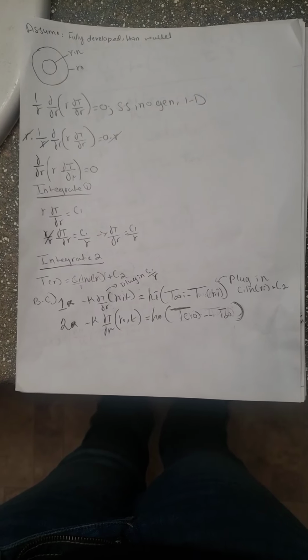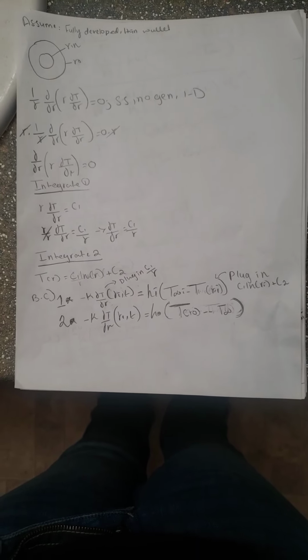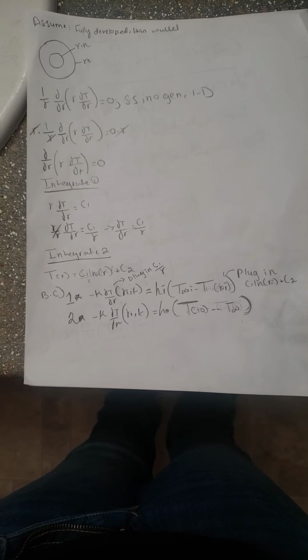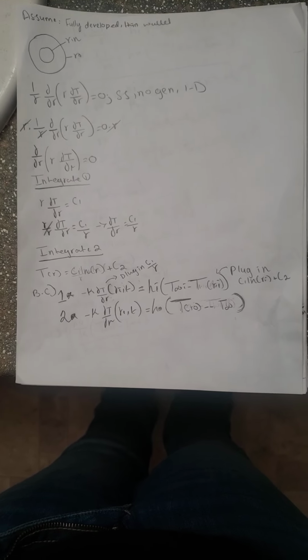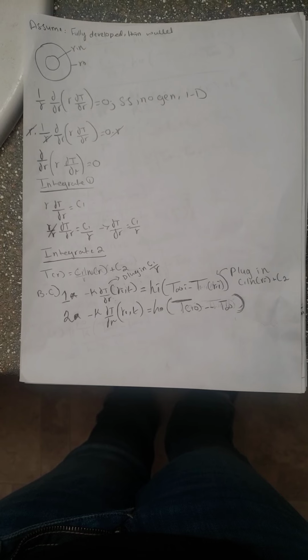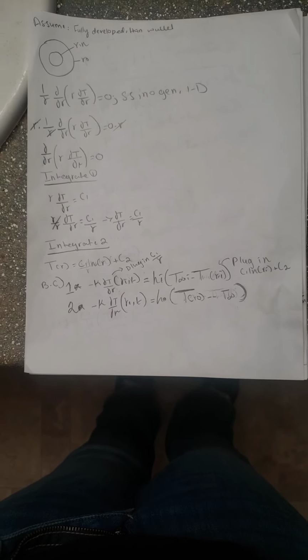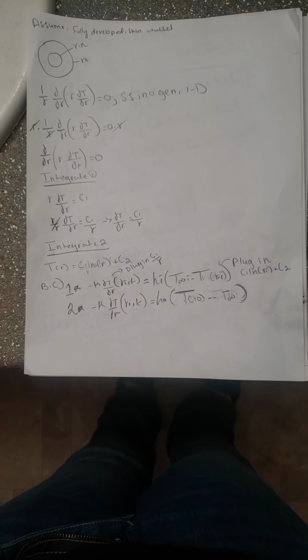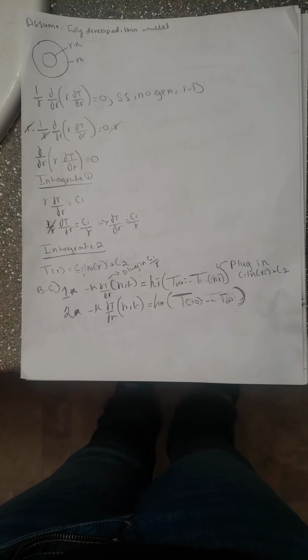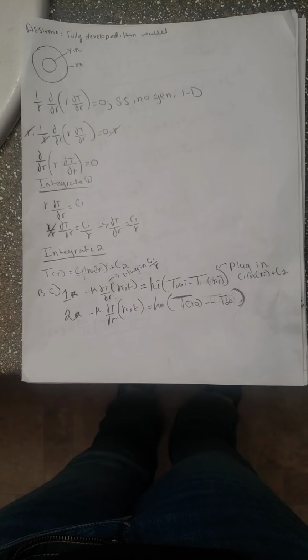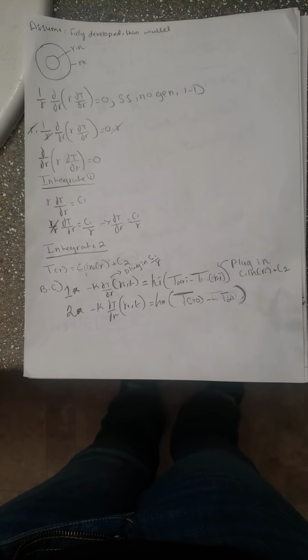I am modeling the outlet pipe of the heat exchanger, which has insulation surrounding it to prevent heat loss. The insulation material that was chosen is rubber, since it's a relatively cheap material that works well as insulation. So this is my conduction equation for the analytical solution.